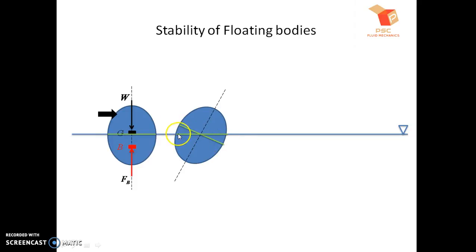And again what we will do, we will draw one line through this free surface, and it shows that when the body has got rotated, some part of the body, which is nothing but this part, has come out from the liquid, whereas some part of the body, which is nothing but this one, has gone down into the liquid. And these two portions are somewhat similar. So whatever the part by which the body came out, with the same part the body is going into the liquid.